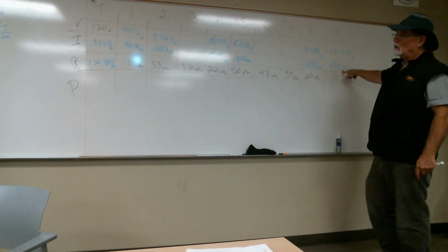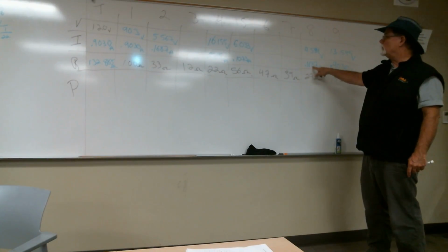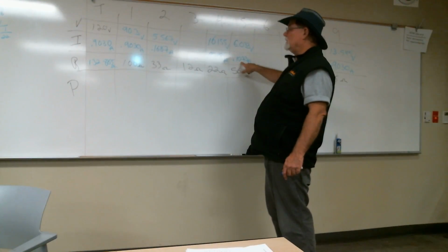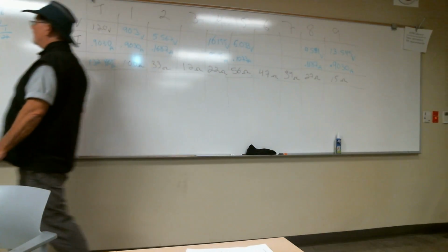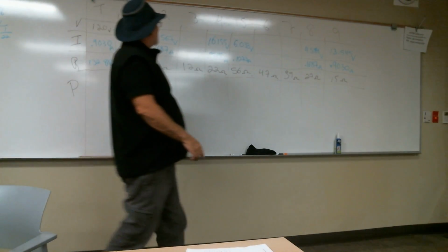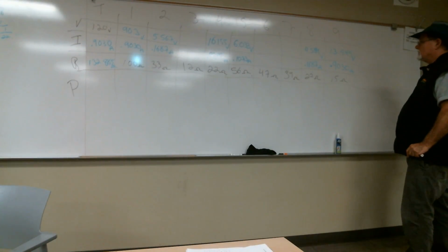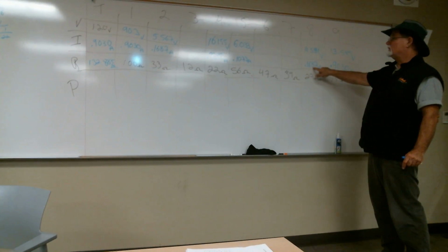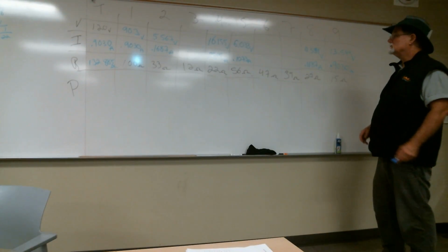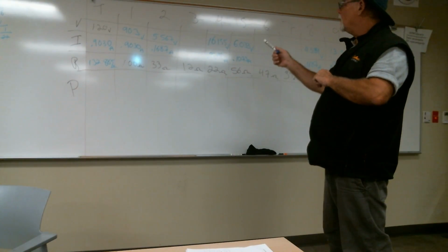It's also got to be less than what's going through 8 and 2, which it is. So now this value tells us what's going through 5, but the remainder of what's going through 8 and 2 must be going this direction, right? So that means I can take either 2 or 8 and subtract this 0.1073 from it. That'll leave us with 0.0614, and isn't that going through all of 3, 6, and 7?